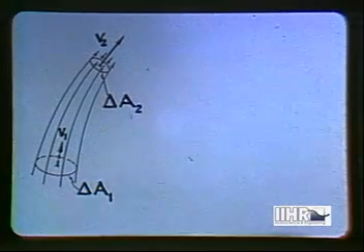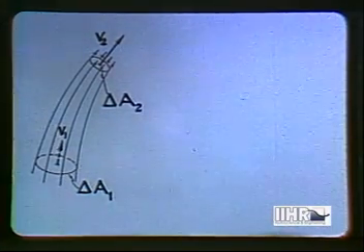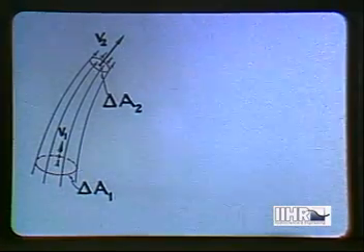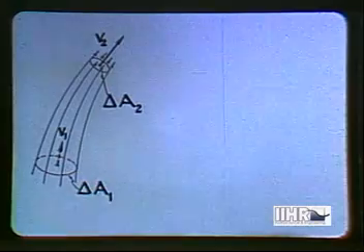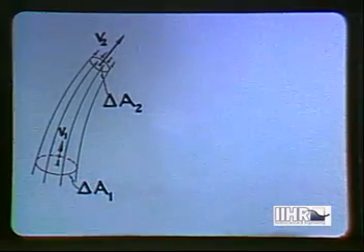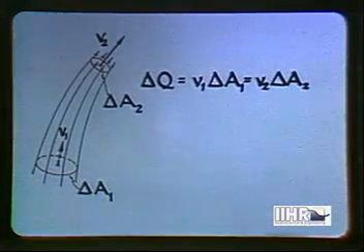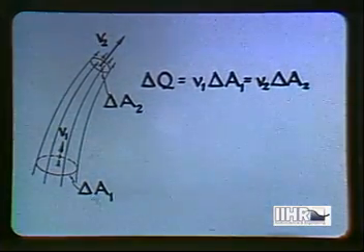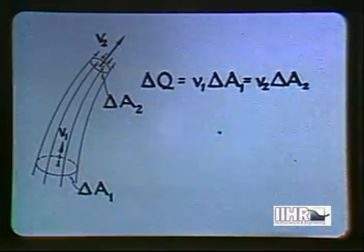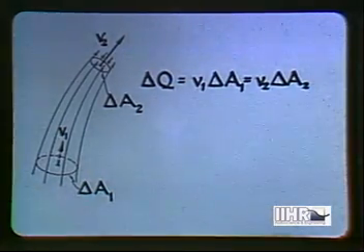The passage formed by a closed surface controlled in shape by a group of streamlines is known as a stream tube, and the fluid contained within it is called a stream filament. By definition of a streamline, there can be no flow through the walls of a stream tube. Hence, unless the fluid expands or is compressed during motion, at any instant the rate of flow past successive sections of the tube must be the same, in accordance with the principle of continuity.